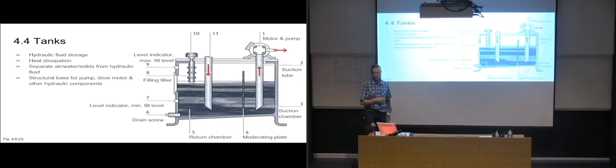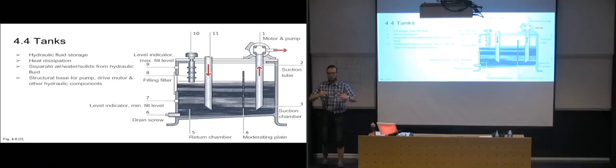So it's the same principle as the low one, where you can actually look in, so that if you're going to fill fluid into a tank like this, like we talked about before the break, maybe you have lots of very large pistons that are being run through this tank. It would be wise to put everything, as much of the fluid as you can, into the system. So extend all pistons and get as much fluid into the system as you can, so that you are at your minimum level here. Check if it's below your minimum fill level. If it is below, you're going to have to fill until you at least can see some liquid in the level indicator. And then you do the opposite.